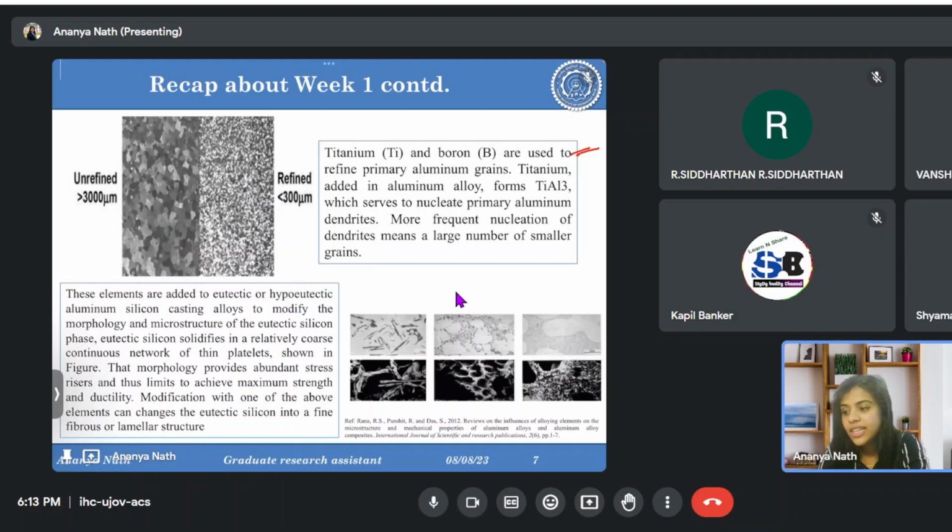They are refining the grains because pure aluminum has a lot of ductility. It's a ductile material, so the strength of pure aluminum is not that much. To use aluminum for different applications, we have to have a bare minimum strength in it. That's why we go for different strengthening, and this is how, by mixing different constituent elements, we can enhance the strength or hardness of aluminium.